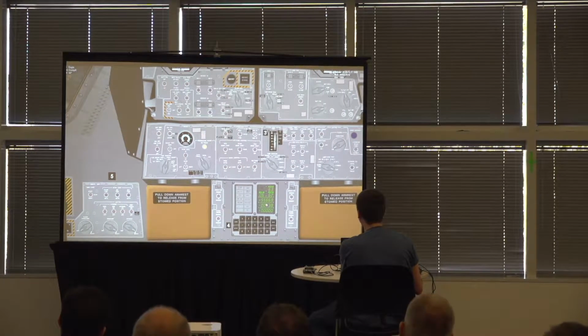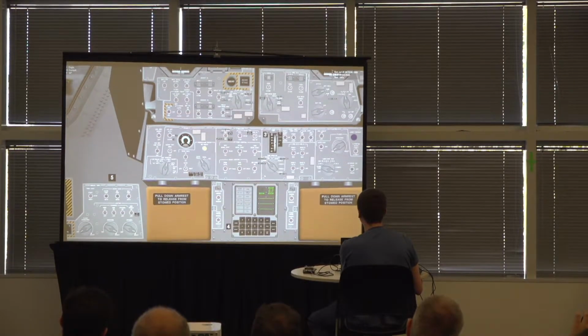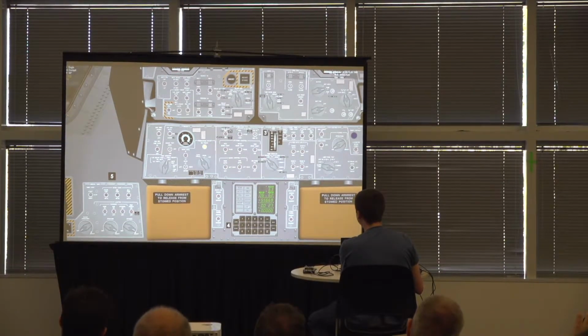So at ignition minus 35 seconds, we're going to get a blank on the DSKY. And that is my cue to arm the descent engine. And now a routine called Average G is running. Average G is what takes our accelerations and feeds them into our state vector, which is our position and velocity as we fire the engine. So our display right now, we have the countdown in the middle. The top line here is our surface relative velocity, 5,567 feet per second.